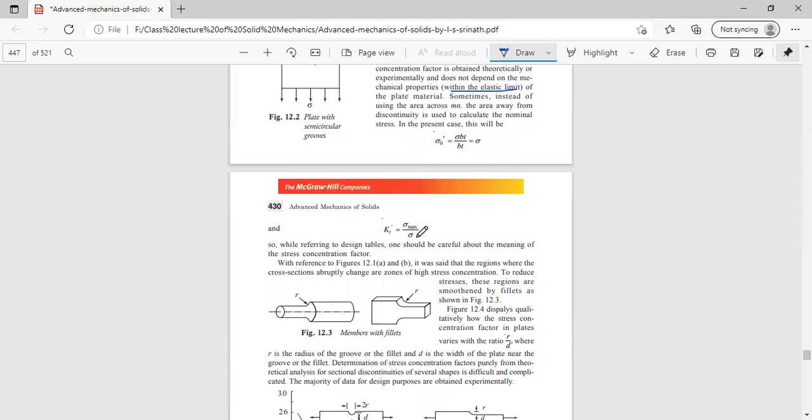Although sigma max may not be equal to sigma, because we are considering sigma max as the maximum stress induced anywhere in the beam itself, may be or may not be in the cross section M-N. So sigma max may not be equal to sigma itself.